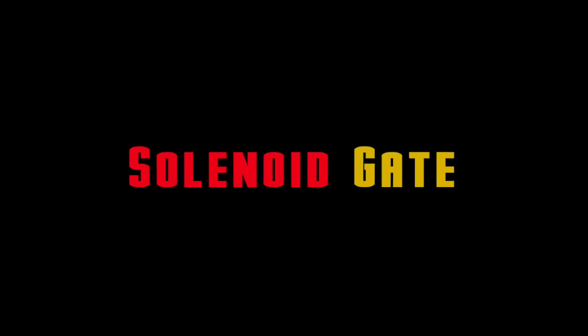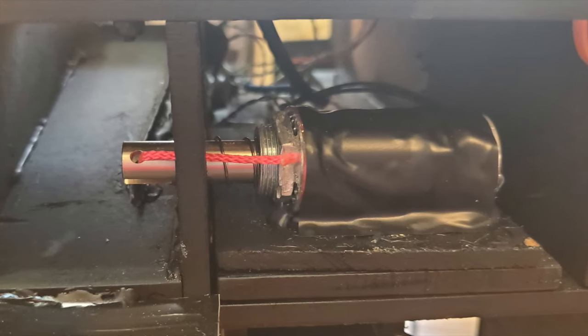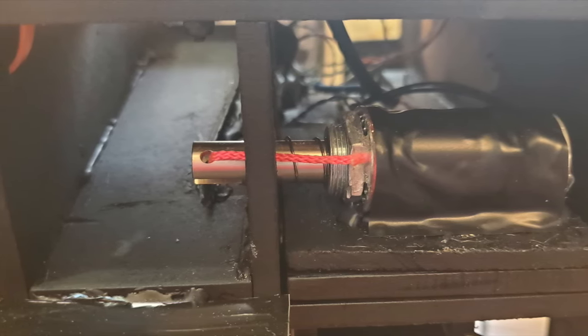For deploying sensor decoys, the solenoid gate has been chosen. The solenoid acts as a door that opens and closes for each of the decoys to come out at the right time. The solenoid has been slightly modified with a spring and a string. The spring compresses when the solenoid is activated and decompresses when it's turned off.